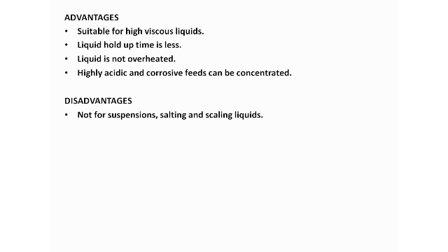Disadvantage: not for suspension. For concentrating the suspension, this type of method or equipment cannot be used, nor for salting solution as well as scaling liquid. Poor feed distribution in the tube, because the feed is moving only via the gravitational force. So the space near the inlet will have more liquid, whereas the tube space far away from the inlet will have less liquid.